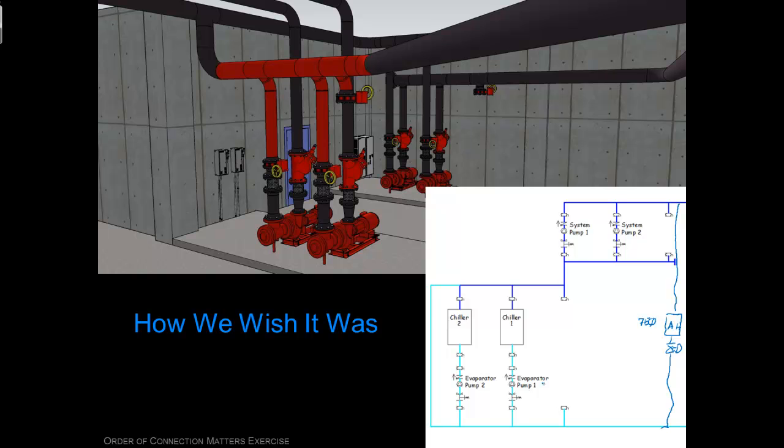Each chiller is running at 500 GPM. So we get to this first T. There's 750 coming in. Since this chiller's taking 500 of it, it takes 500 GPM of warm water and puts it through the chiller. That chiller is running at full load.